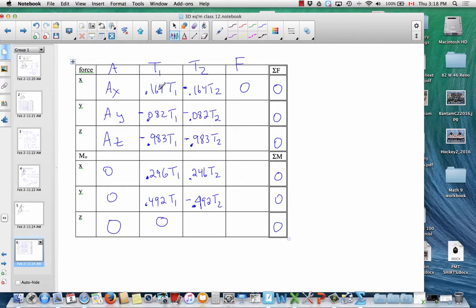Okay, so components of AX, components of tension and force. We didn't mention that earlier, but it's got a Y component, which is positive 550 cosine 15, and a Z component, which is negative 550 sine 15. For its moment, there's only an X moment. You just go straight up for the R vector and then cross it with the force. It's a negative X moment. The perpendicular distance is 2.5 meters, and then the perpendicular force is the 550 cosine of 15. Sorry to squeeze that in there. Okay, so those are our conditions for equilibrium.